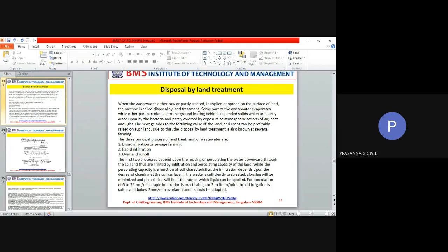And even in cities, if there is no way that you can use the treated wastewater, you can use it for what is called groundwater recharge. So this water has been treated to so much degree that it does not have very high polluting capacity. Now, so much wastewater is there. You don't want to use it for agriculture. You don't want to use it for your landscaping, nowhere. Then the next best thing that you can do with it is allow it to reach your groundwater table.